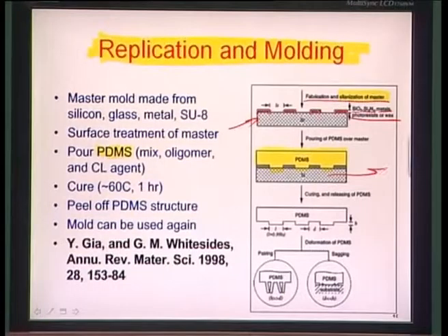So what you do here is you pour the PDMS from the top side as if it has been cast over the mold which you created in the previous step, and then you essentially heat cure the PDMS. So the idea is the mold can now be taken off after this is cured, and this can be separated like the negative PDMS piece of the mold. So whatever is there on the mold surface, the negative of that is transferred onto the PDMS surface.